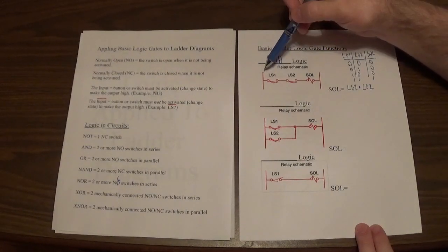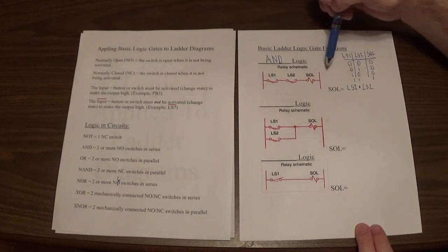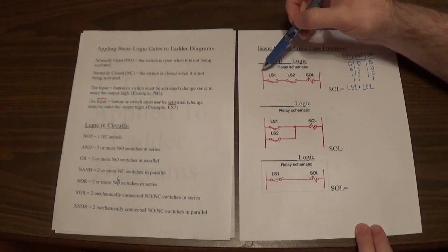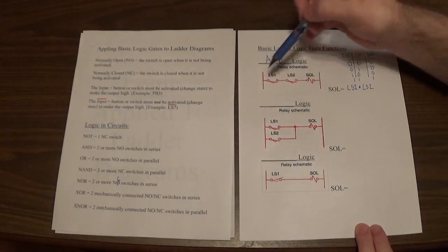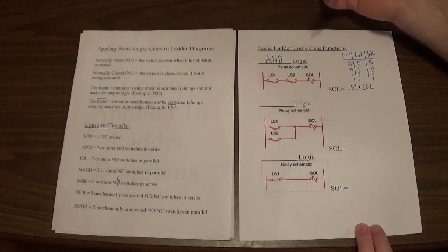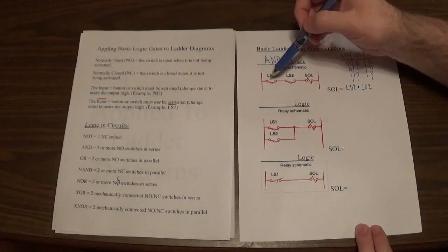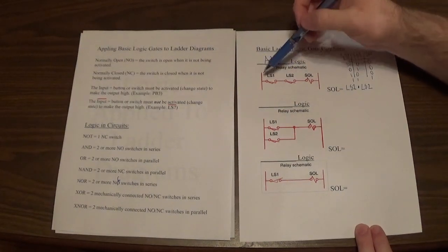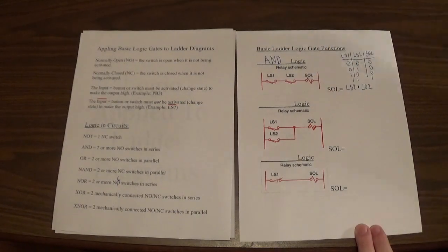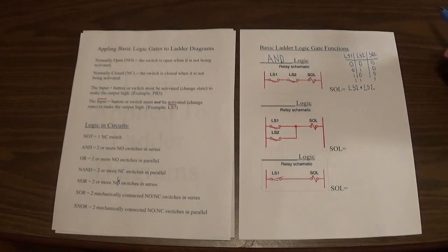Okay? And just to back up here for a second, in case you're not familiar with the motor control ladder logic, so these rails are your power. So this can be positive and negative if it's DC, or this can be hot and neutral if it's AC. So closing the switches, we have to have a complete path of current flow in order to energize that output. Okay, so that's how that works.